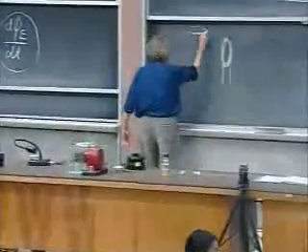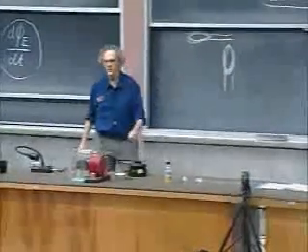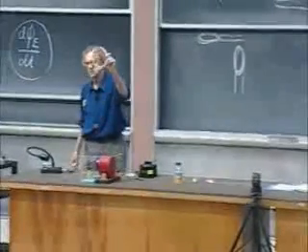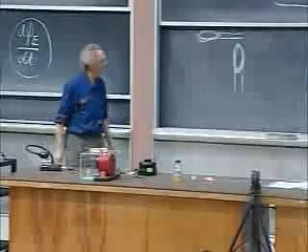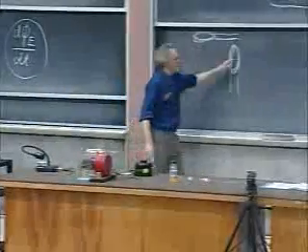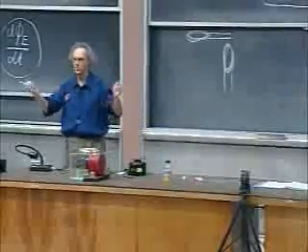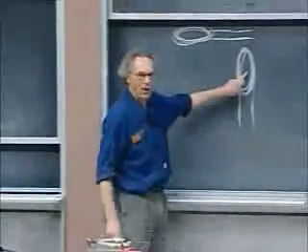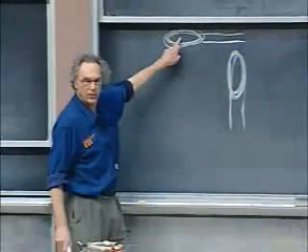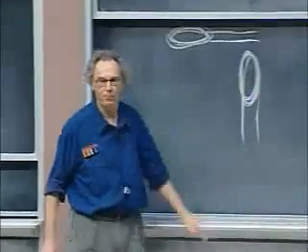And here we have one, also going to run 60 Hertz AC through there. Here's the coil. This one is easy to show. The other one, very heavy. These two currents are 90 degrees out of phase. Not 120, but 90. So it's a two-phase current. So when the current is maximum through this one, it is zero through this one. When it is maximum through this one, it's zero through this one.